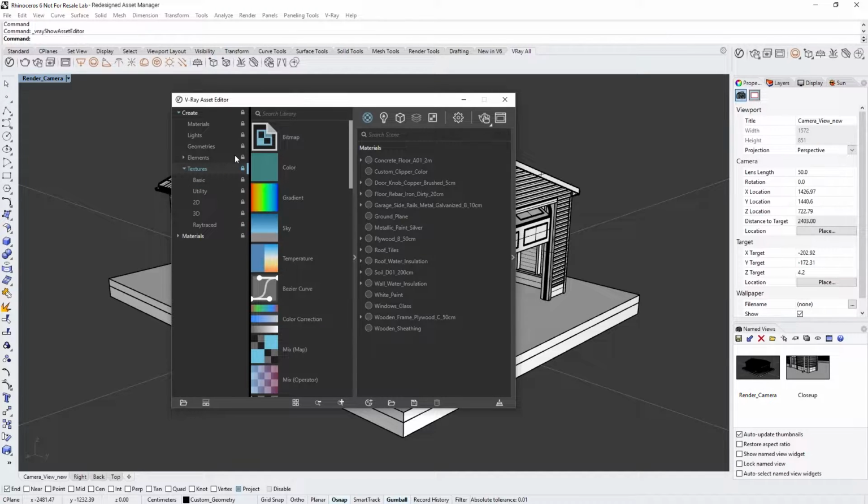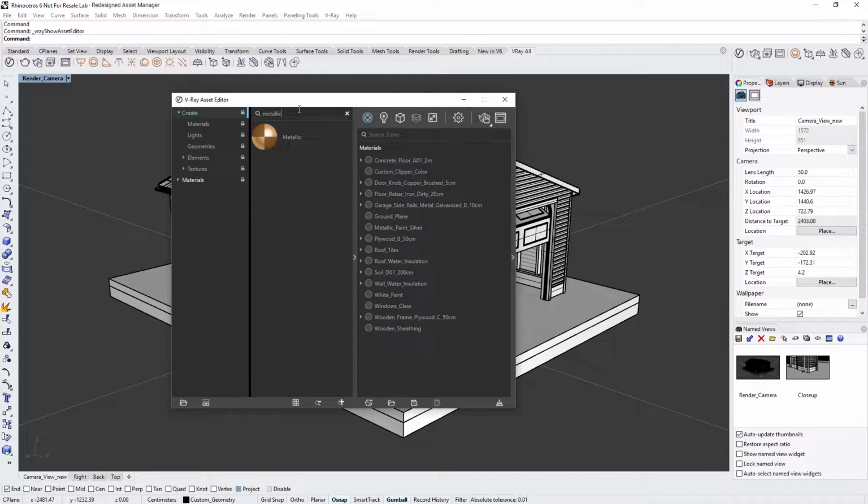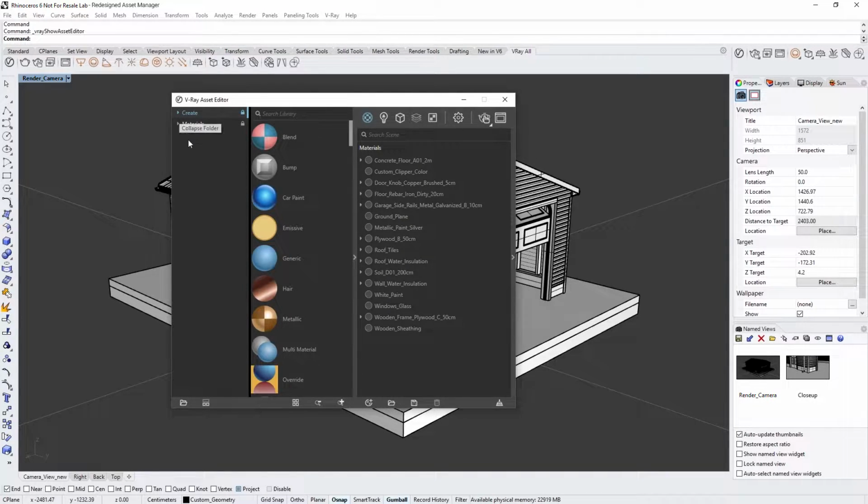For example, I can look for curve options in the Textures category, or I can search all categories if I select the Create menu. In this case, let's search for a metallic material, which we can use to create PBR shaders. Together, you can use whichever of these options you find most convenient for your workflow. Right below the Create menu, you will find a library of materials that come with V-Ray. We have different types of materials organized conveniently into different folders. Just like with the Create menu, you can quickly search within these different categories or the entire material library itself.